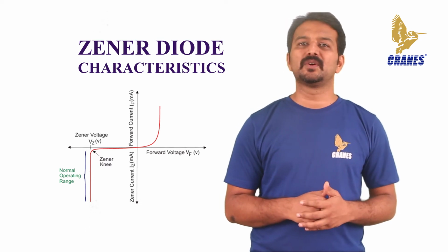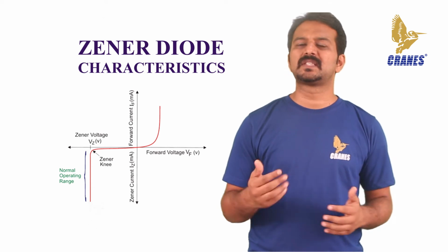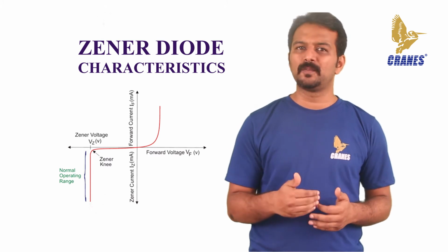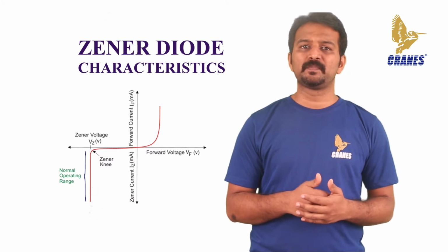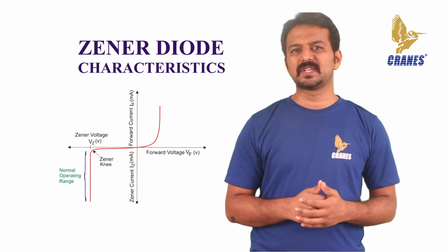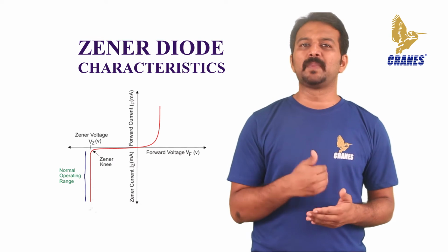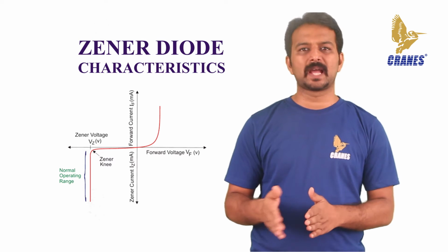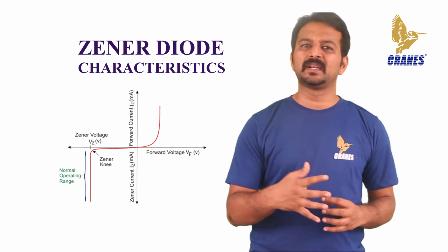The Zener diode, or breakdown diode as it is sometimes referred to, is basically the same as the standard PN junction diode, but it is specially designed to have a low and specified reverse breakdown voltage, which takes advantage of any reverse voltage applied to it. The Zener diode behaves just like a normal general purpose diode consisting of a silicon PN junction when biased in a forward direction, that is, anode positive with respect to its cathode. It behaves just like a normal signal diode passing the rated current.